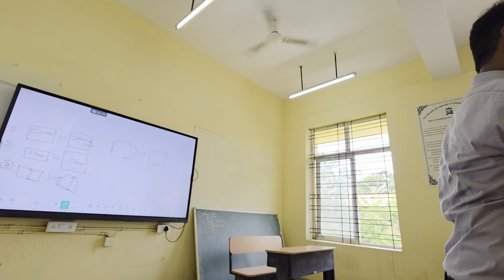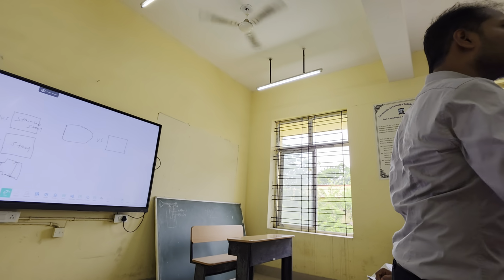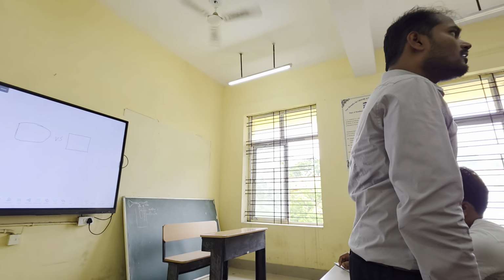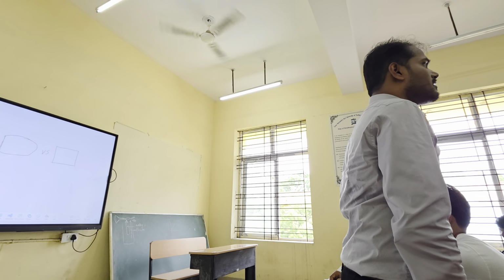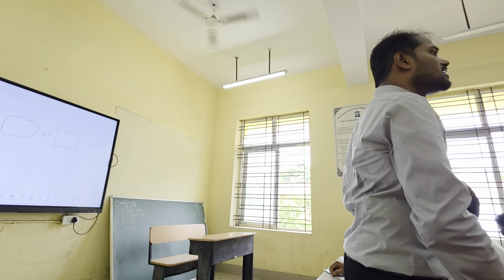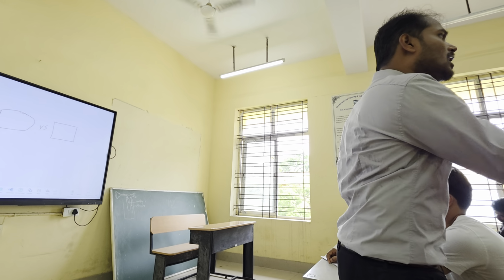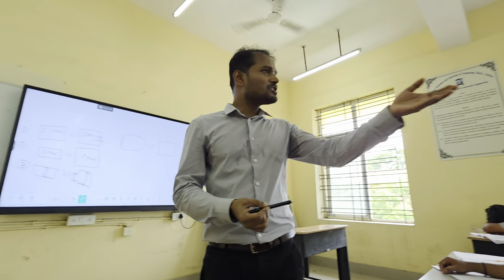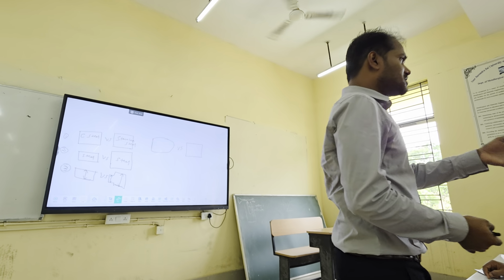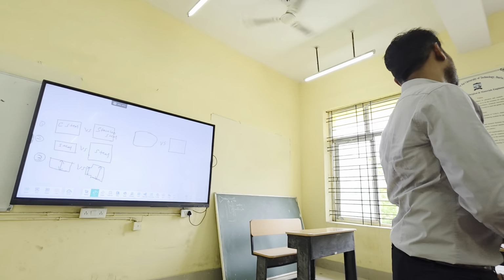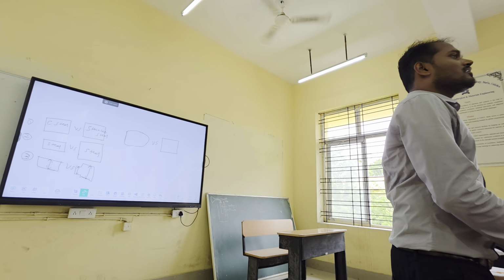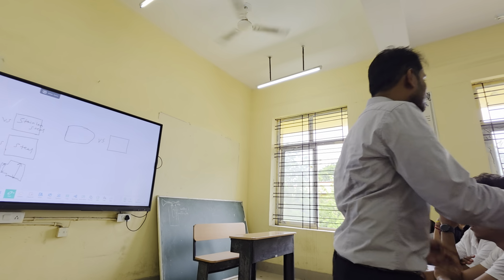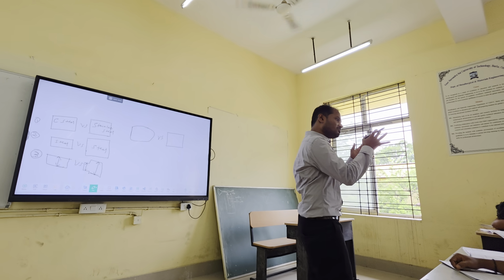And you know that because of lattice strain also the strength increases. That is one of the fundas. If you want to increase the strength, then you can produce lattice strain in the body. Automatically strength will increase. Why? Because the lattice strain cannot allow the dislocation to move easily. They are a hindrance actually. So that is your martensite. Because of formation of martensite, there will be a lot of lattice strain in the body. That increases the strength. That is also why we do solid solution strengthening, because a lot of lattice strain will generate.